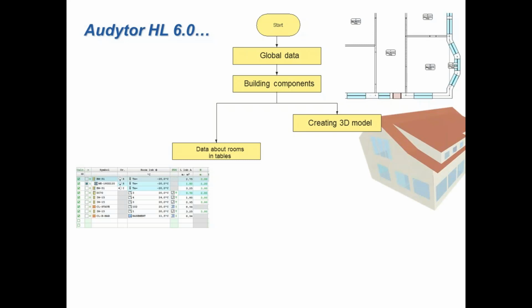But as you see, we create not only the 3D model, but first of all, we create the flat plan view. Generally, most of the time, we draw on the flat plan view, and the third dimension, in most cases, is created automatically by the program. That's simply faster and easier. Only in some cases, like in the case of attics, we use the full 3D editor.